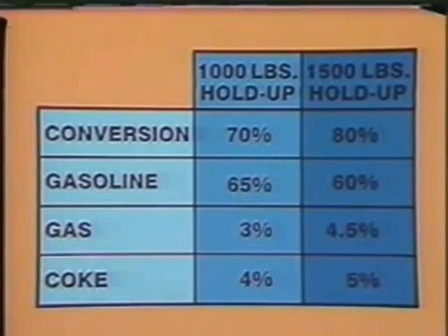When the catalyst inventory in the reactor is increased, there is a corresponding increase in conversion. This, however, may not be desirable because increasing the contact time between the oil and the catalyst often leads to overcracking. When the oil is overcracked, less gasoline is produced in return for higher gas and coke yields.